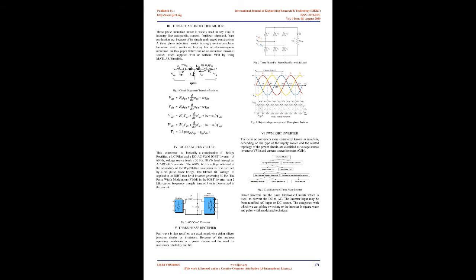In principle, all modulation schemes aim to create trains of switched pulses which have the same fundamental volt-second average as a target reference waveform at any instant. The major difficulty with these trains of switched pulses is that they also contain unwanted harmonic components which should be minimized. Three main techniques for PWM exist. These alternatives are: 1. Switching at the intersection of a target reference waveform and a high-frequency triangular carrier, double-edged naturally sampled sine triangle PWM. 2. Switching at the intersection between a regularly sampled reference waveform and a high-frequency triangular carrier, double-edged regular sampled sine triangle PWM.